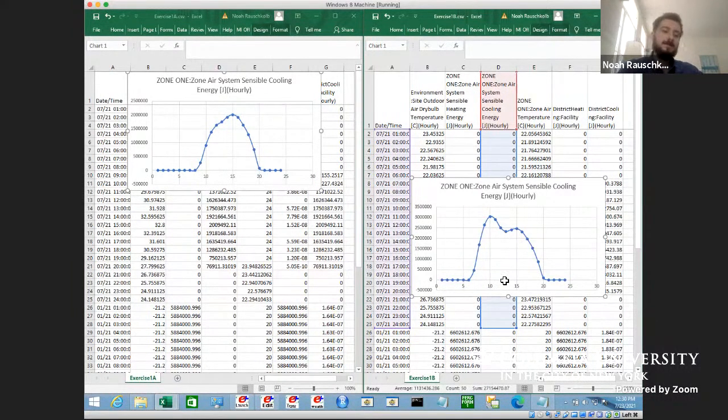If you look at a Google 3D view of that building in particular, there's a huge amount of shading from adjacent buildings. It actually affects not just your annual energy, but your peak loads, because there is a big tall building south and west of it. So that kind of thing can matter a lot.